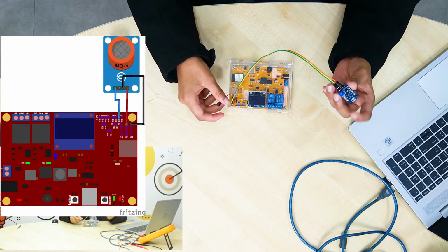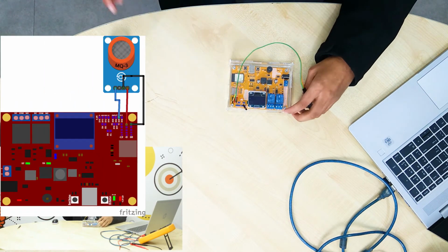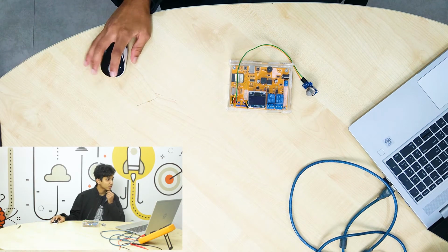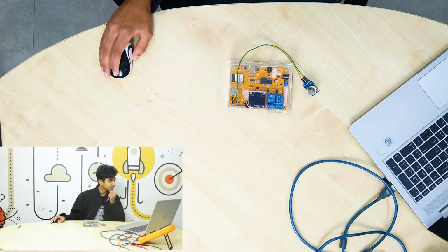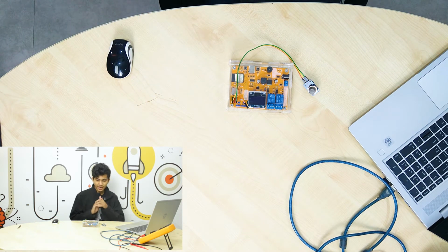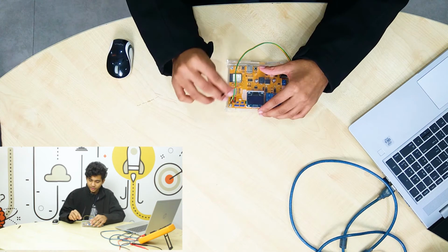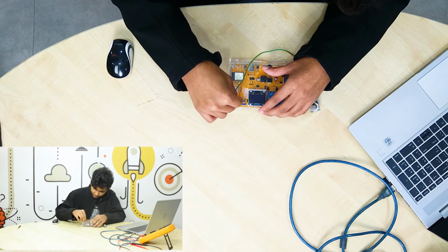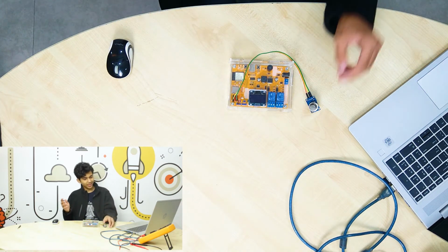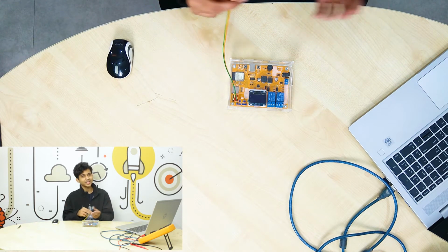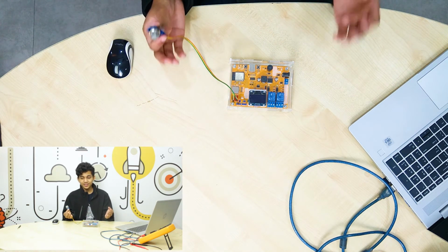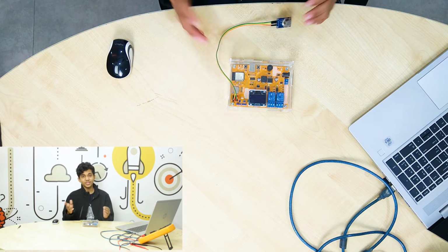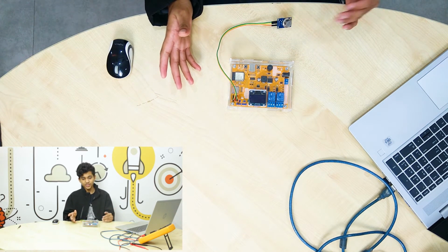Then let's connect our analog input pin. For that, we need to check our code. According to our code and circuit diagram, it's pin number 39. So let's connect it with pin number 39. Where is pin number 39? Here it is. Well, it's as simple as that. We don't need anything else. And by this, we can measure the amount of pollution that's in the air. And after that happens, it's going to notify us.